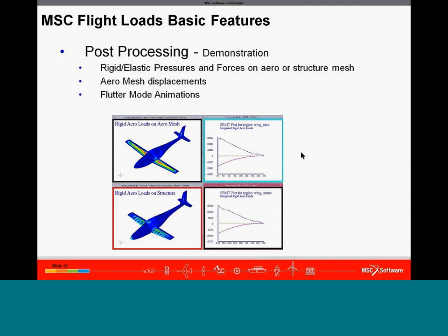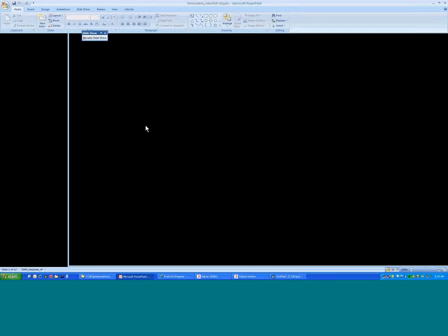I'm not going to demonstrate it today, but there is a tool in Flightloads, something called the Loads Browser, where you can create shear moment torque plots as a post-processing step. It doesn't actually use the monitor points created from Nastran, but it uses the actual loads Flightloads computed by the Nastran solution, and it post-processes them on the fly to create VMT plots and such. So I'm going to go through and give you a brief demonstration of the 3 bullet items shown here.